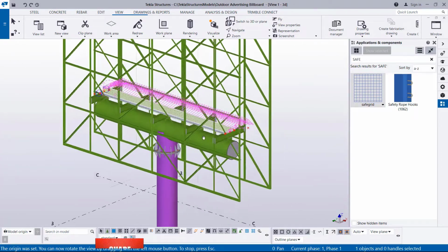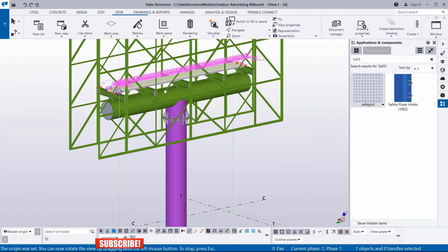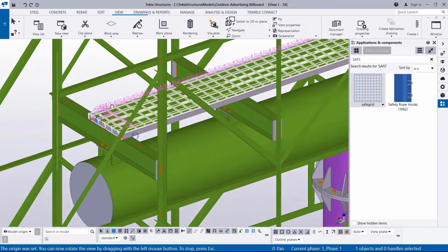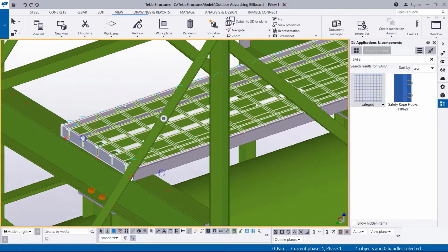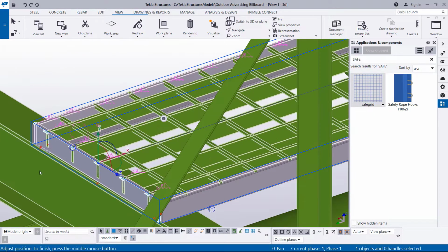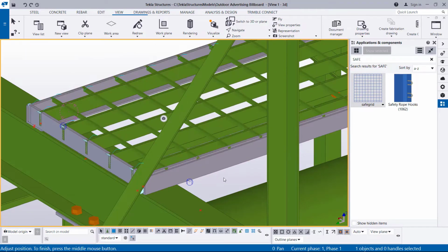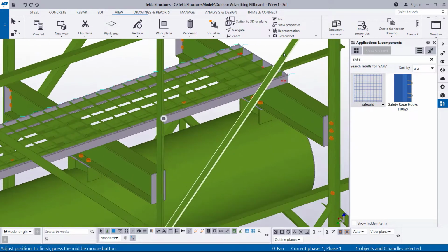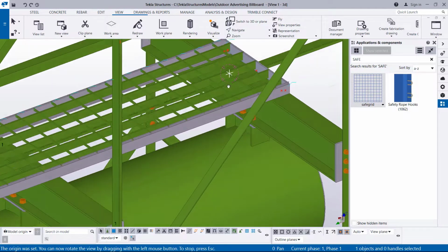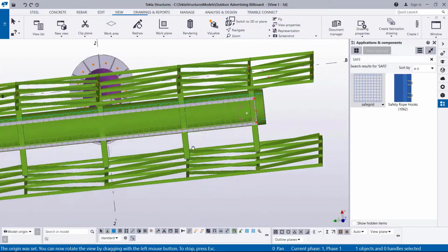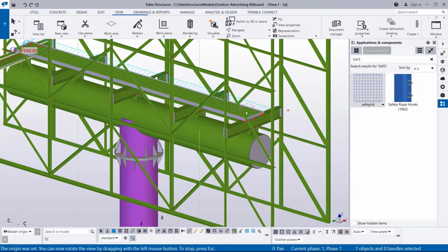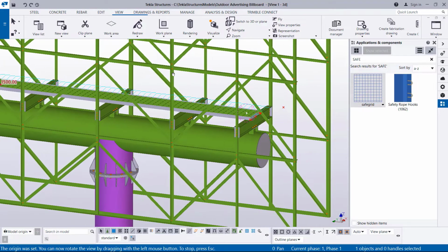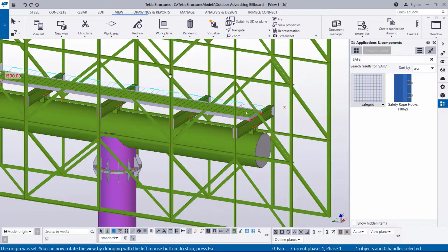If the site location has issues, or has become expensive, you can dismantle it and go and assemble it elsewhere. So that's why on top of the platform here, I've just created the grating. The grating will be confined within the bolted angle profile on top of these beams you're seeing here. Now I've placed my grating or platform on top here. I can just turn that round so that you can see the platform. This platform's main purpose is just to provide a standing space or an area for the erectors to do the erection and also to fit the canvas.